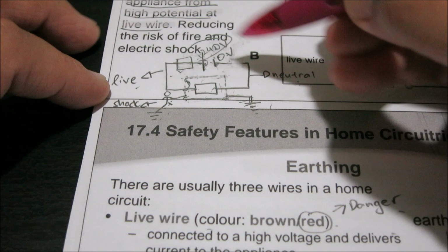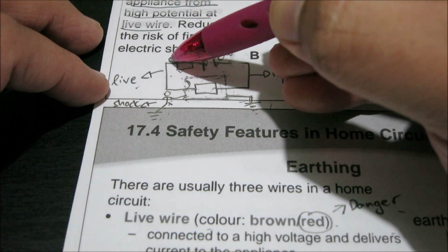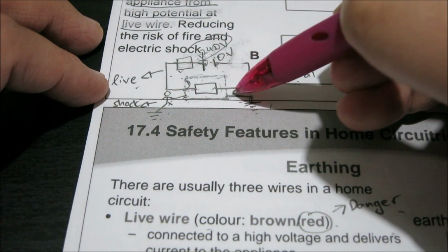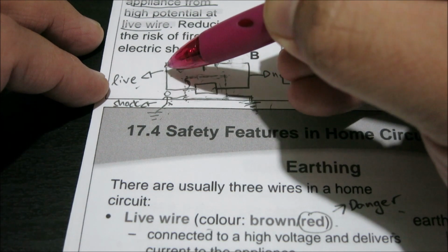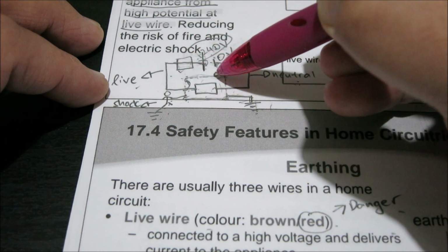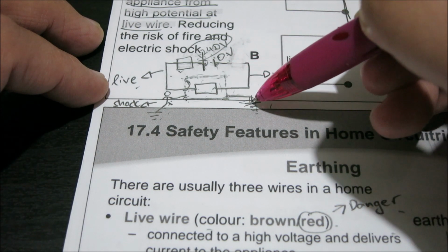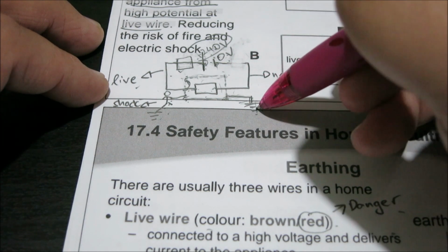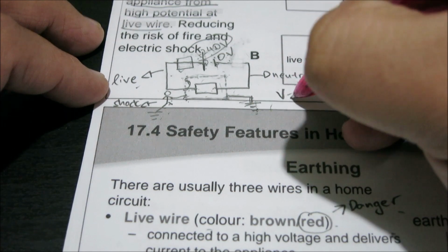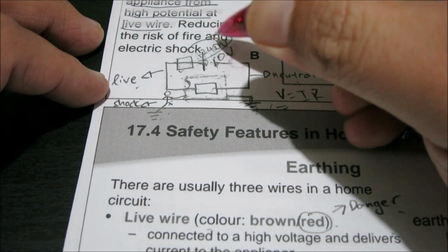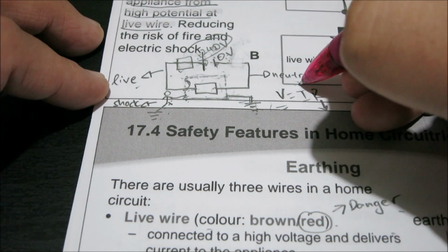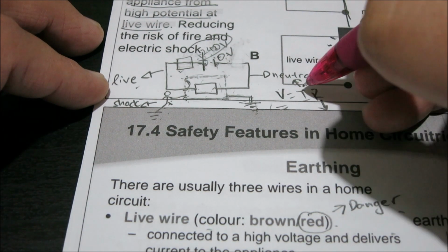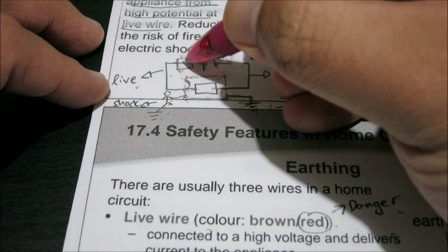Now, the earth wire also has two functions because once my current flows here and down through the earth wire, there's basically no resistance along its path. Wires, zero resistance, connects down to the metal casing, no resistance, earth wire, zero resistance. So when resistance drops, V equals IR, provided my voltage remains the same, where my resistance drops to almost zero, my current will shoot up. So when my current shoots up, then your fuse will blow.